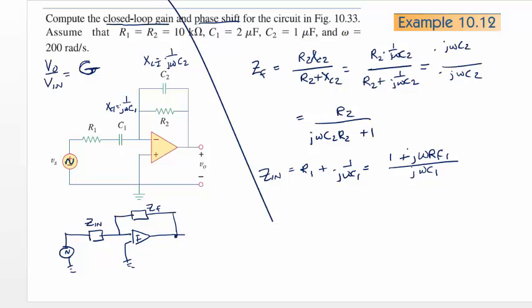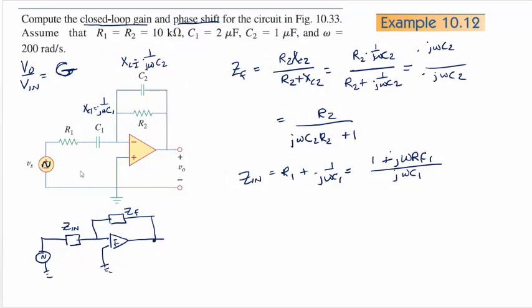Okay, so we obey the op-amp rules. So this is V in right here. This is 0 volts right here. And by our op-amp rules, this is also 0 volts. And this is V out over here, and of course it's V out relative to a ground connection, if I were to connect up my oscilloscope or multimeter there. So I'm going to say current going into the node equals current going out of the node. Draw my current going in, current going out right there.